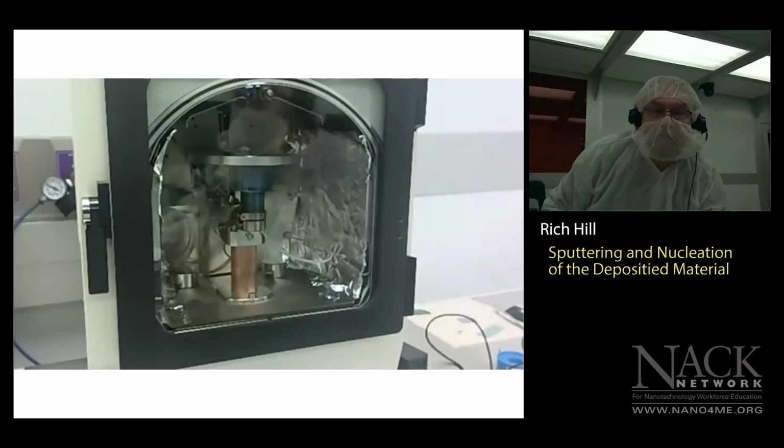Okay, well, it finished putting down 3 nanometers. Now it's venting. What's nice about this system is it vents really nice and quick because it's all automatic. It's got all these solenoid valves inside. All of our other systems in our clean room here at SUNY Erie take time because we don't have the same kind of venting possibilities. But this system is great for that.